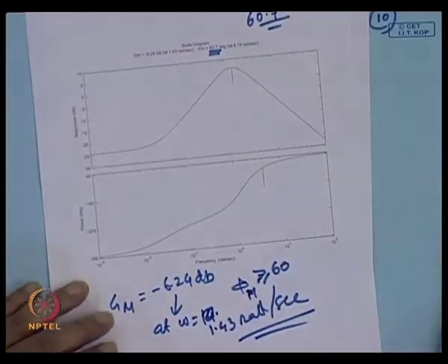So, this verifies the statement we made in LQR control: the phase margin is greater than or equal to 60 degrees, and the gain margin is infinity, and also a reduction by a factor of half is allowed. We will stop here today.